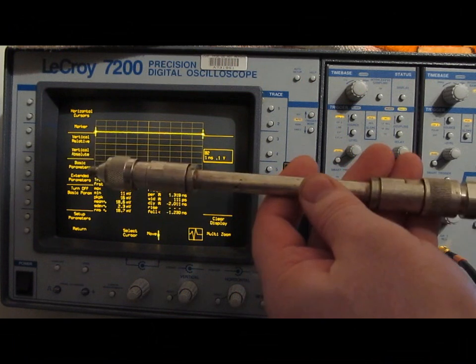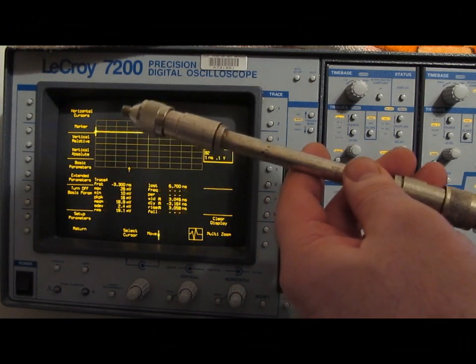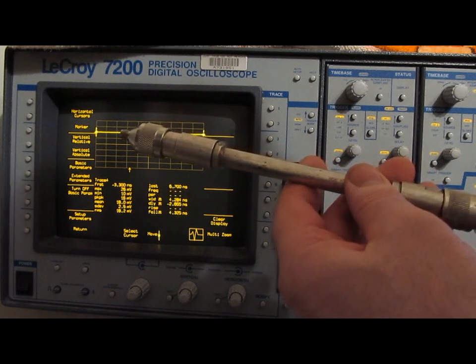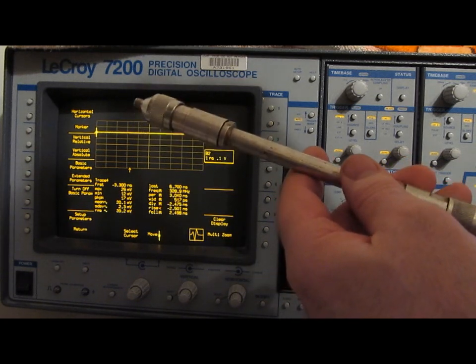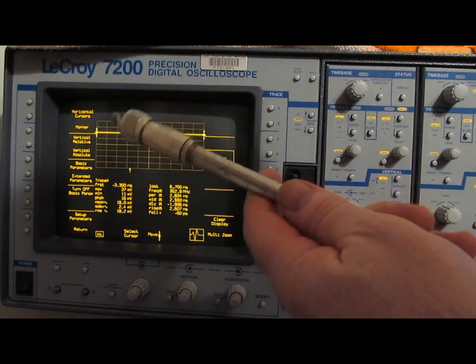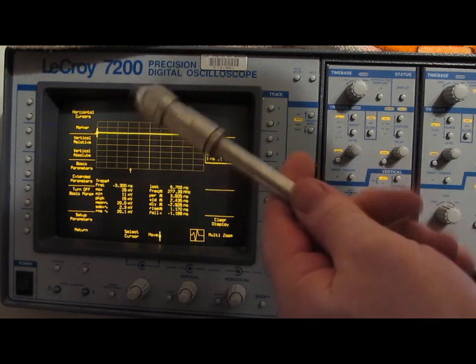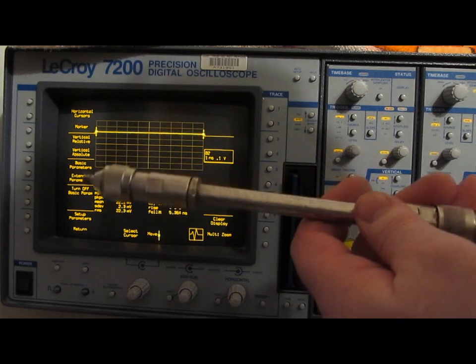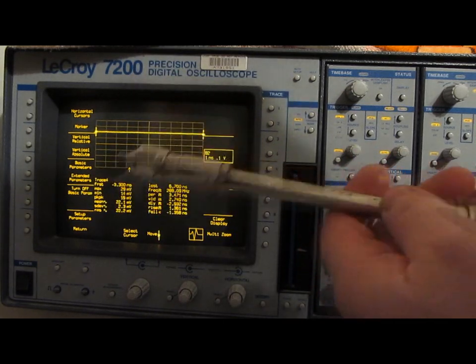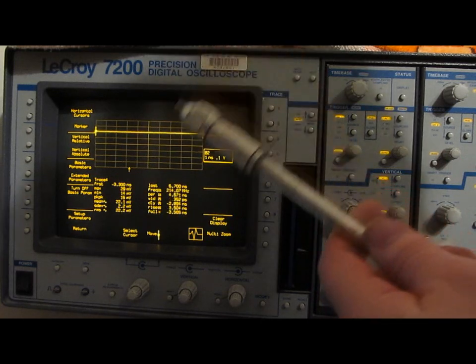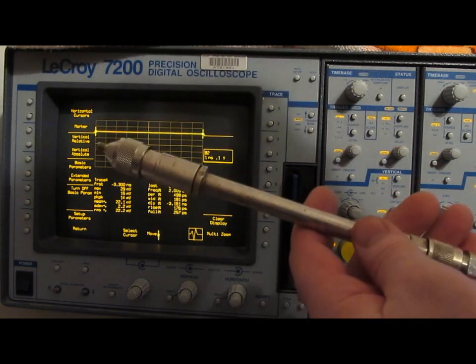Again, the LiteVNA is rated for 6.4 gigahertz. That would give us a rise time of 156 picoseconds. Using harmonics, they cap it off at 9.3 gigahertz. That gives us a rise time of 107 picoseconds. With the one that I own, I seem to get reasonable data up to about 8.4, 8.5 gigahertz, so somewhere around 120 picosecond rise time.